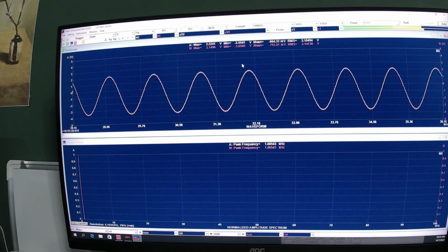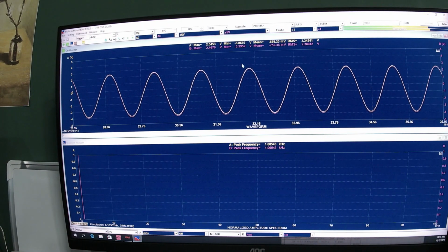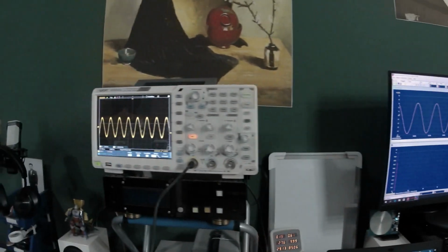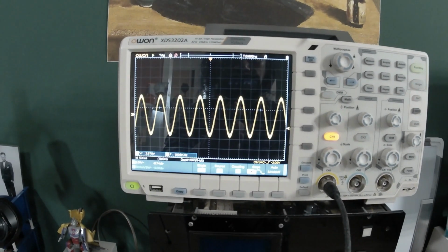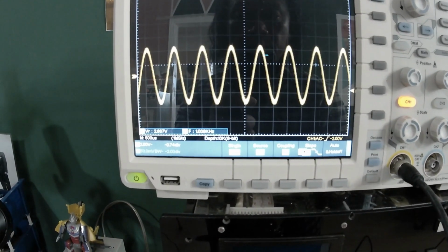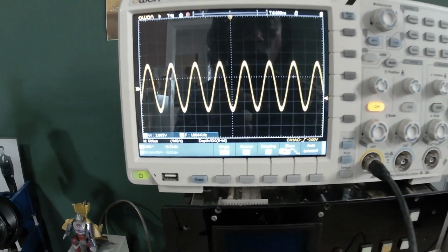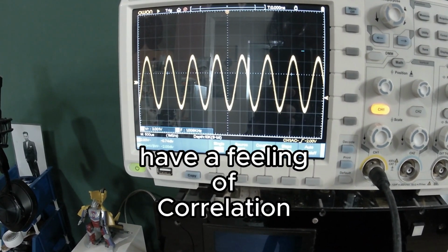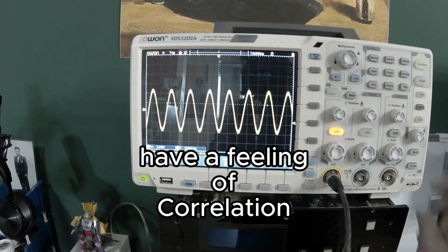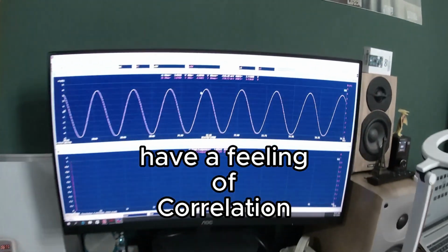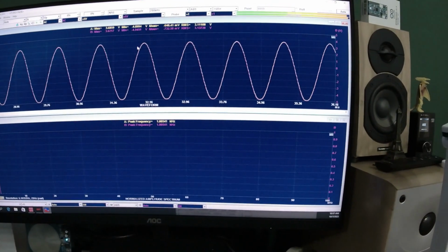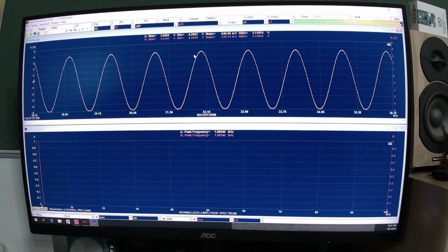I need 2.8 volts voltage swing on the resistive load. This is the capture of the PC, and again I'm comparing that one with the capture from the standard oscilloscope. It reads here 2.6 volt RMS at 1 kilohertz. I may need to increase the amplitude to something like exactly 3 volts is okay, 2.9 is okay, and that's it. And what's the reading in here? There seems to be 1 volt difference. But anyway, as long as the measurement is standard, that's okay for me.